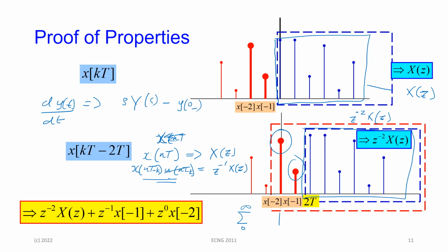If it is not causal, then for x(n-k) I have my z^-1 X(z), but I have some other values that I'm going to have to bring in inside of there. If k is 1, then we have a z^0 x(-1). If it is 2, then we have something looking like this. If it's 3, we'll keep expanding.